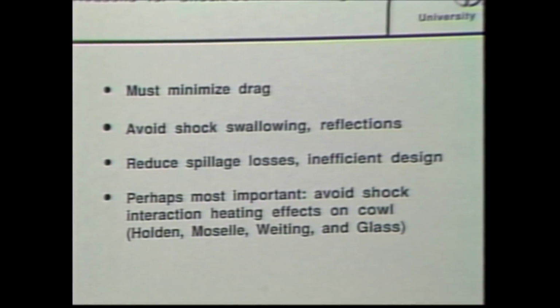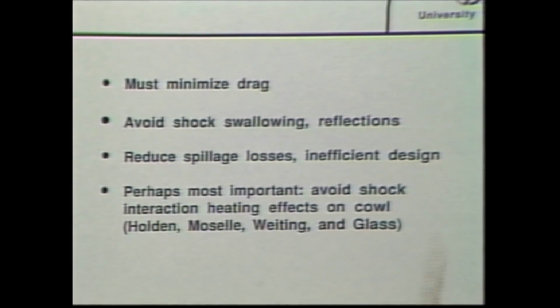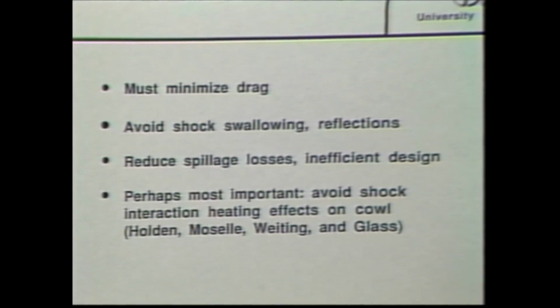Right. First, reasons for wanting to match the shock to the cowl. You want to minimize drag in all these hypersonic configurations. You want to avoid swallowing the shock, because if you do, it will reflect on the engine and probably induce deleterious effects. You want to avoid spillage. That means you want the shock to be pretty close. You don't want it to be far below the engine. But at the same time, you probably don't want the shock to be exactly touching the lip, for reasons that we'll see in a few moments. So that's probably pretty tight criteria.